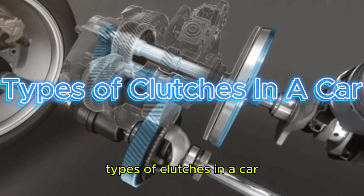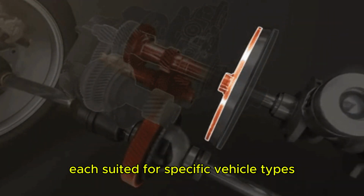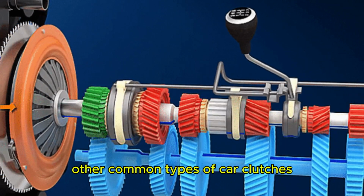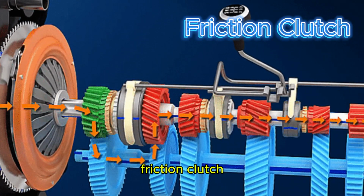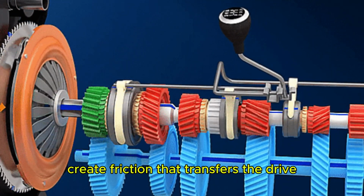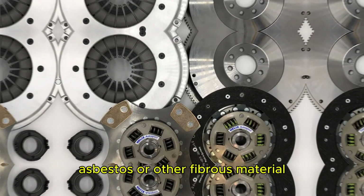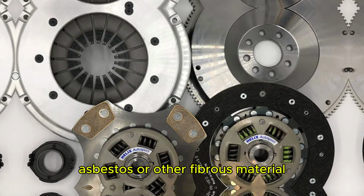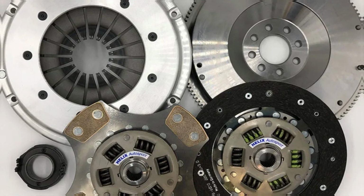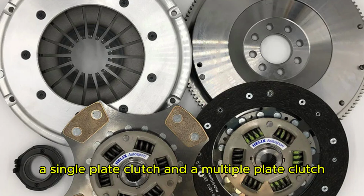Types of clutches in a car. Car clutches come in different types, each suited for specific vehicle types, driving styles, and transmission systems. Below are the common types of car clutches. Friction clutch. In this clutch, surfaces attached to the driven and driving shafts create friction that transfers the drive. These surfaces are lined with cork, asbestos, or other fibrous material. Cars with friction clutches need to have the linings replaced periodically. The friction clutch is of two different types, a single plate clutch and a multiple plate clutch.